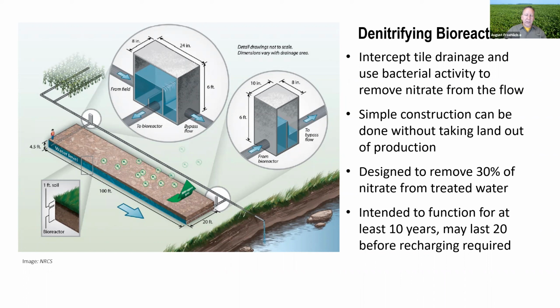There's a lot of "it depends" in this. There are many variables, like temperature and the size and the arrangement. So those things impact what the actual reduction of nitrate is, but it's significant. And the design standards aim for a 30% reduction, but I've seen statements of 50% reduction or more.